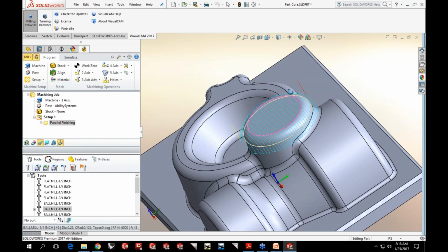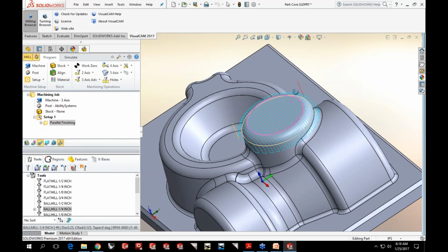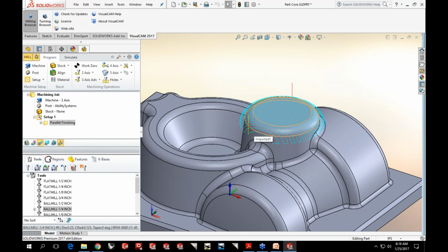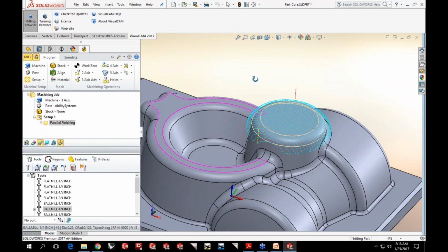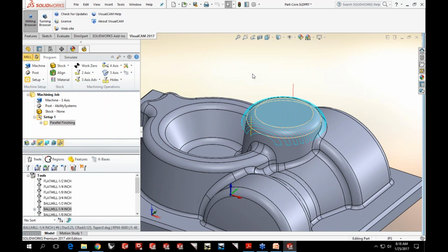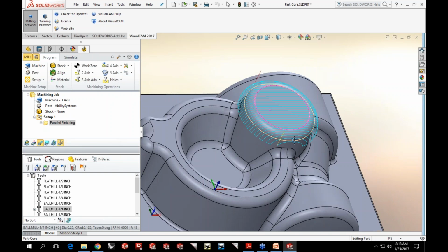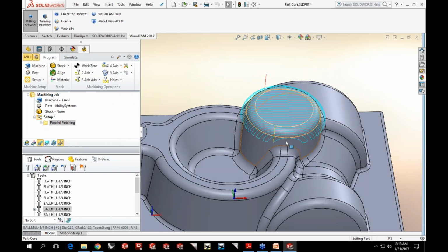And it also checks against the adjacent surfaces, so the tool path will never cut into adjacent surfaces. So we have 3 different options. You could do on condition, where it stays up to the geometry. To will stay completely inside, and then go past. In this particular case, using past would be more ideal for programming a feature like this.